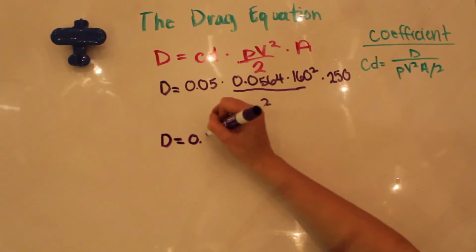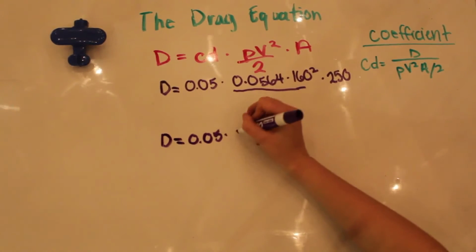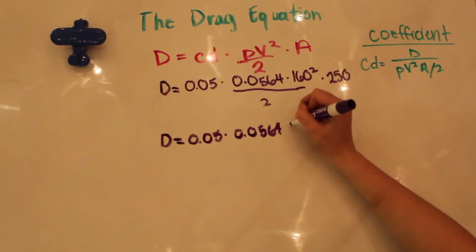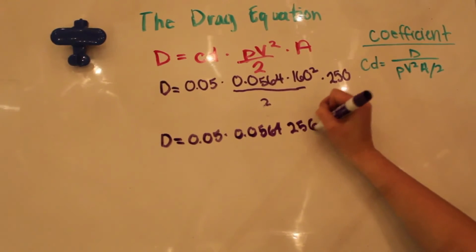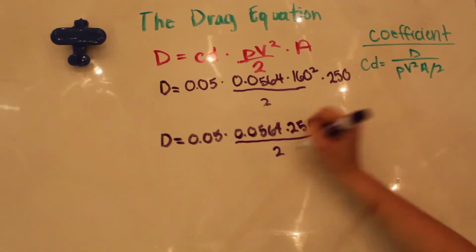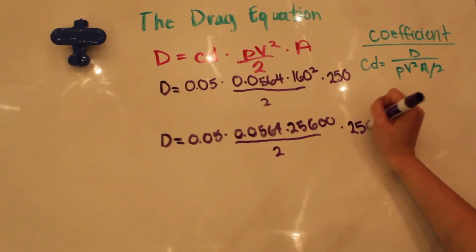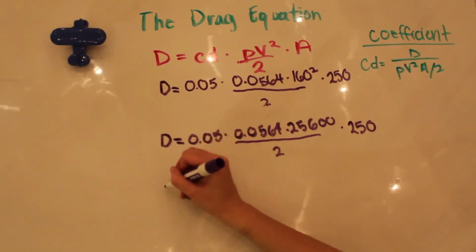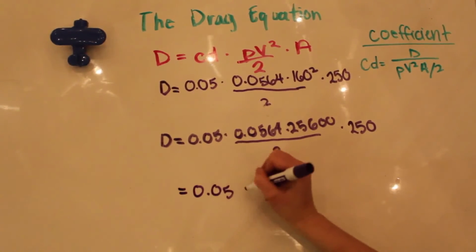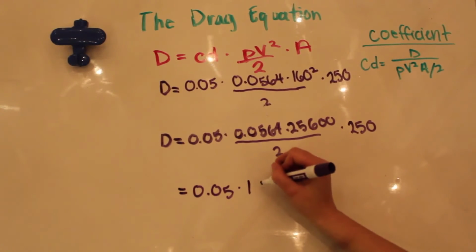A light aircraft typically sticks close to 10,000 feet. The density is a bit more difficult to calculate because you have to take into account the pressure, 29.292, the temperature average at 10,000 feet, which is 23 degrees Fahrenheit, and the dew point, 13 degrees Fahrenheit, which is how much water is in the air. I used a density altitude calculator, and we came out with 0.0564 pounds over feet cubed, rho.